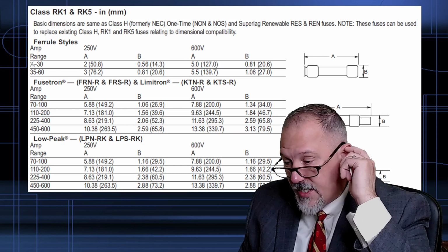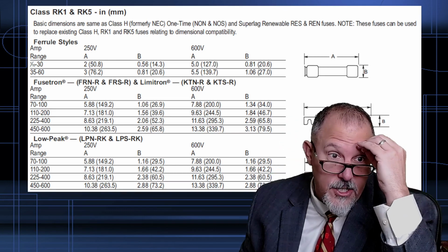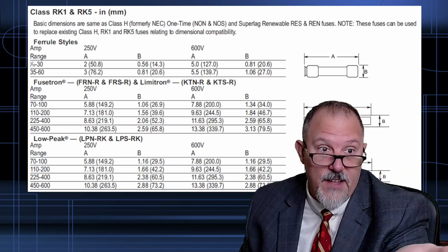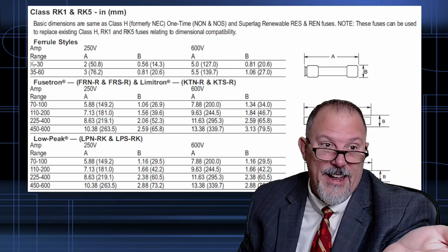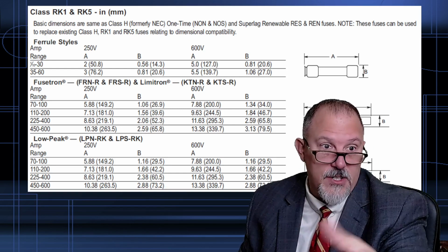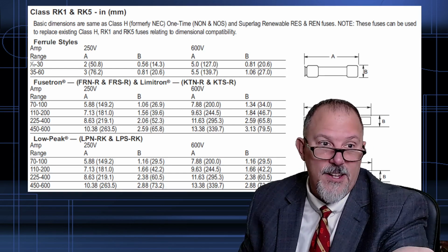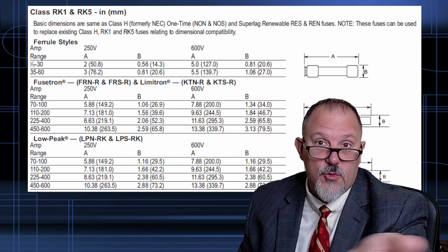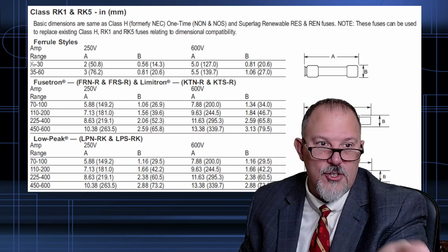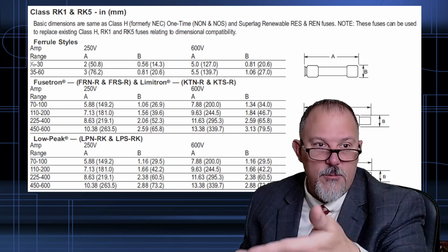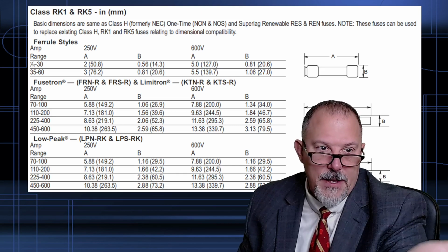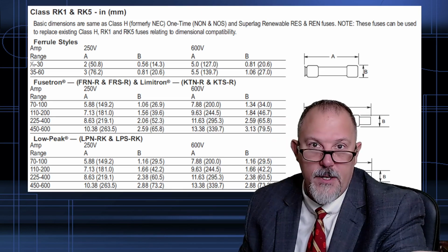That's why whenever we say, I know we had this discussion about a 250 amp, I think it was, or we wanted a 225 amp fuse and switch combination, but so many standards would have to change because they don't make a 225 amp switch. You go from a 200 amp switch to a 400 amp switch. So if you wanted a 225 amp fuse, you got to move to a 400 amp switch to be able to put that 225 amp fuse in it. And that's why we got 601.